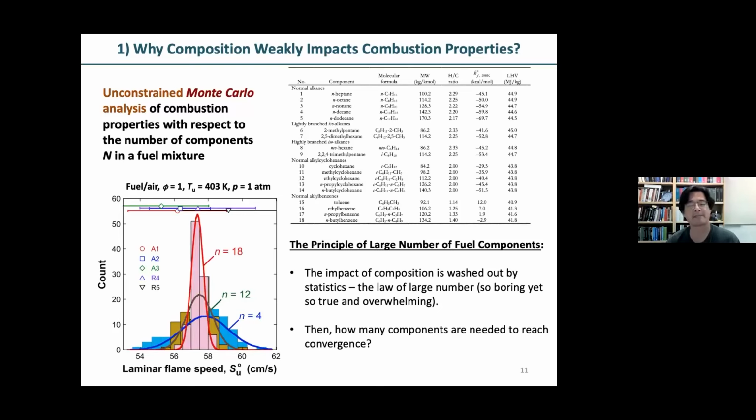You look at the structure of this flame, you find that where the flame is intense, as marked by chemiluminescence of electronically excited CH, this is where the blue flame is. It's somewhere here. Your temperature is already very close to the adiabatic flame temperature, the final flame temperature. But look at this. This large fuel, n-butylcyclohexane, is long gone, finished, disappeared, before the flow reaches the flame. So where did the fuel go? It went to ethylene, it went to hydrogen, it went to methane, and it went to propane.